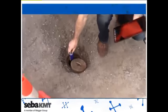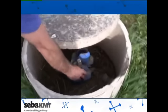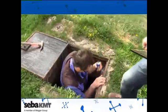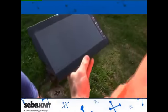Multi-correlation. Setting out the sensors. When programming the sensors, we choose between night measurement and immediate measurement and select a time period before the start of the measurement. The sensors are set out at the individually selected measurement points. At the same time, we record the GPS positions of the sensor set points using a tablet PC.